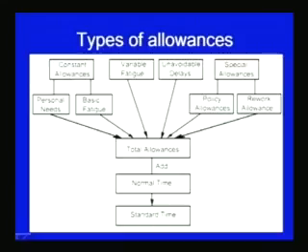So, if you see this block diagram, how we arrive at the standard time after adding the different types of allowances: the allowances are added to the normal time to come up with the standard time. These allowances include the personal need allowance and the basic fatigue allowance, which are part of the constant allowances. Variable fatigue allowance mainly occurs in cases where very heavy work is expected to be done by the worker during the operation, while unavoidable delay allowance is allotted to deal with situations which are beyond the control of the worker, and special allowances are given in the form of policy allowance or rework allowance.